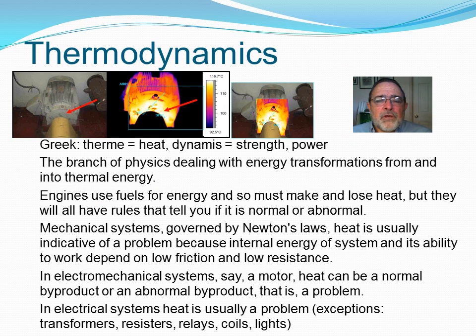Here are 3 images of the same motor. Left to right, this is what we call a real-time or an actual visual image using the visual light range, the infrared thermograph that is used in the report, and then a picture-in-picture image of the same device. The picture-in-picture allows you to see in context what the problem is and exactly where the issue is. It focuses your attention, much like the red arrows would for the technician that goes back to repair these.